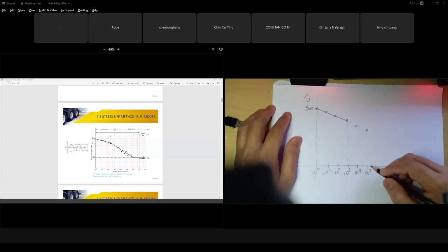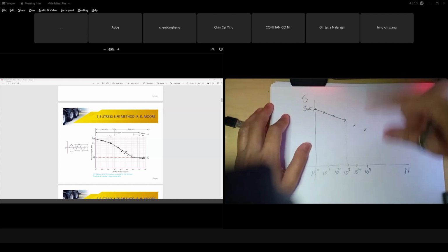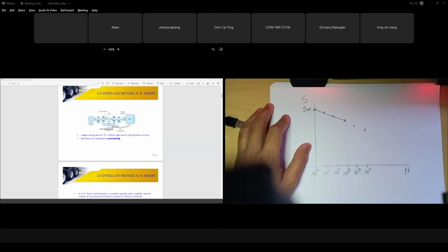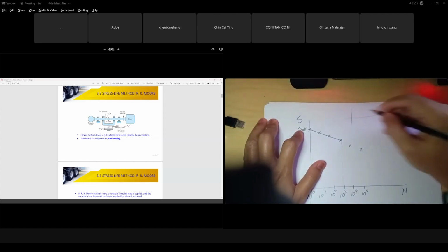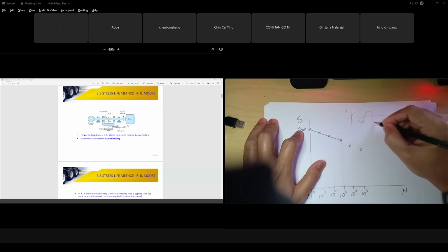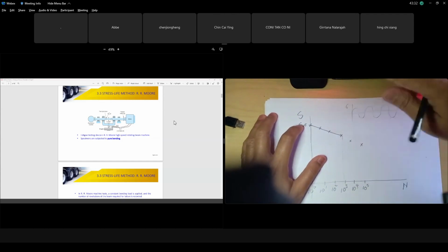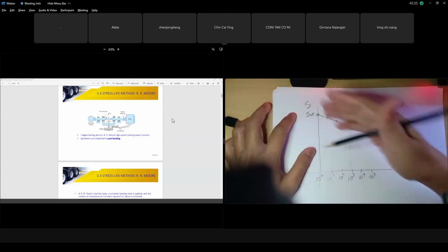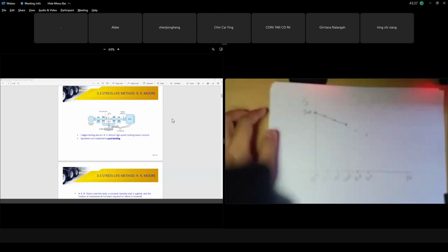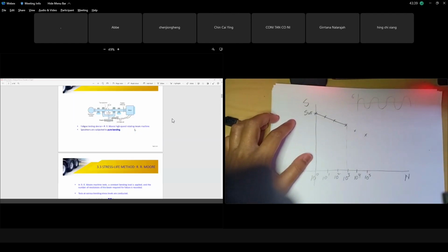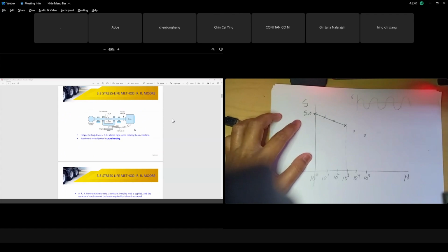And 10 to the power of 4, because this is standard fatigue testing. If you look at this figure, the shaft is rotating, right? The shaft has a bending load. It means the element of the shaft has compression and tension, facing sigma bending tension. This is pure bending, tension and compression while the shaft is rotating. That's what it means. So there is the plot of strength versus cycle. Okay, this is standard fatigue testing.